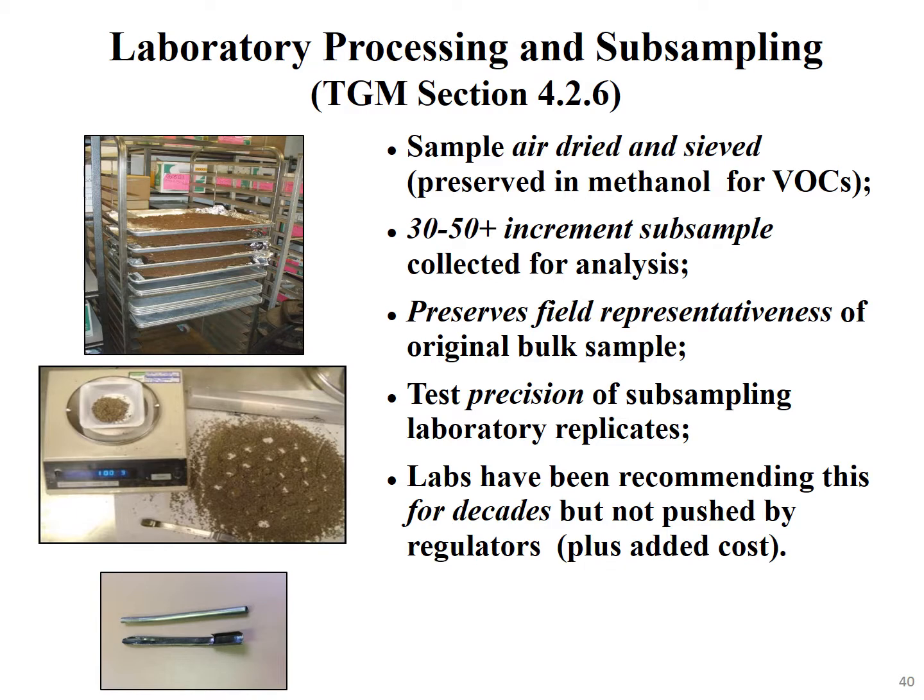This slide is illustrating the lab subsampling process, and as we mentioned earlier, it's very important that the lab follows up appropriately with your MIS sample, because you don't want the lab to negate all that work you've done in the field collecting your multi-increment sample by just opening up your large bag and taking a little hit off the top of that bag and analyzing that, because they would not be getting a representative sample of what was in that large bulk sample.